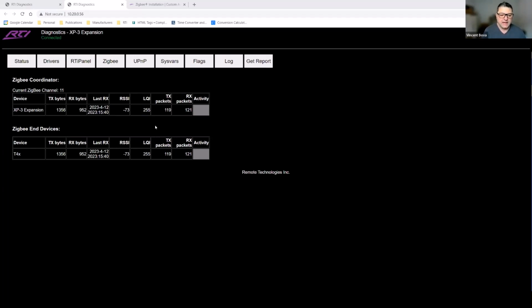Again, RSSI, you want to see numbers anywhere below -75. Anything in the 90s, -90 and up is pretty bad. -100, there's absolutely no signal whatsoever. So that's the story about the statistics. Sorry, that was a little long-winded, but it's really important. That's why I wanted you in on it, my man.